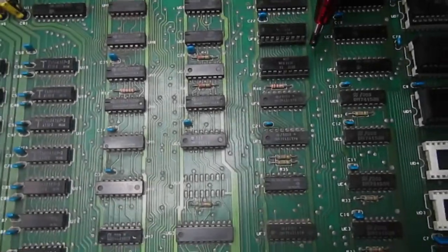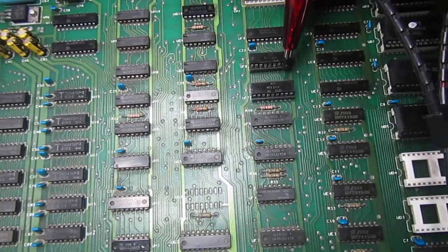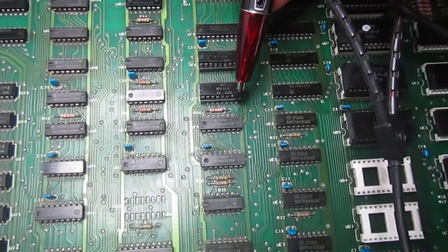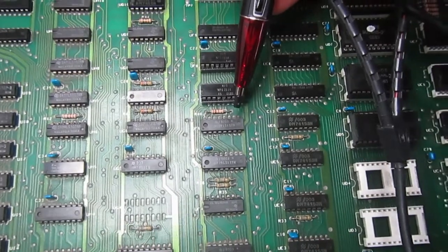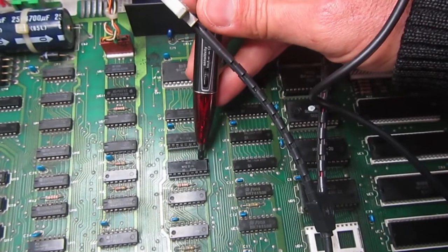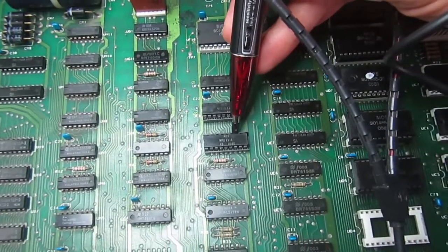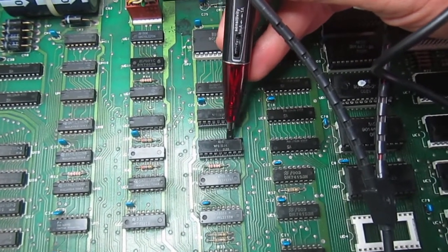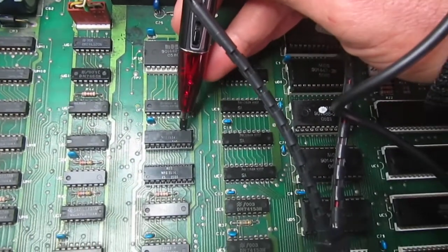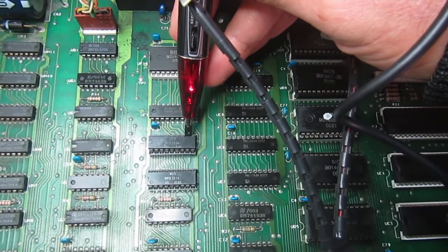Okay, between the two possibilities, I decided to investigate first the possible data bus conflict. And the best way to investigate bus conflicts is with a current tracer probe. And this is UF7 RAM data bits, and I see no current spikes. This is UF8 data bits, and I do see the probe lights. I do see high current,